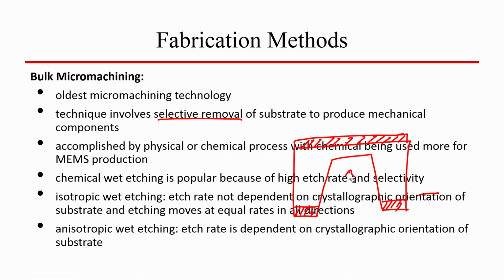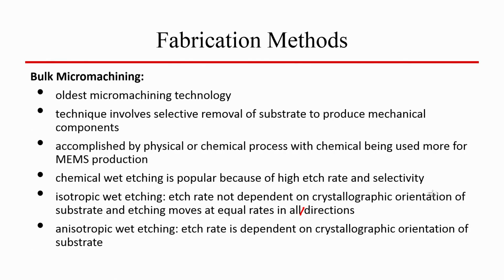Now, here if I have a strain gauge on this silicon wafer, right, these are contact pads, this and these are contact pads, and then this is a strain gauge. So, if I apply a force on this, then what will happen? This diaphragm will bend. This bending of diaphragm will cause the strain in the strain gauge. If it is a piezoresistive material, I will be able to see the change in resistance. So, this is a bulk micromachining technique. It is also used to produce mechanical components.